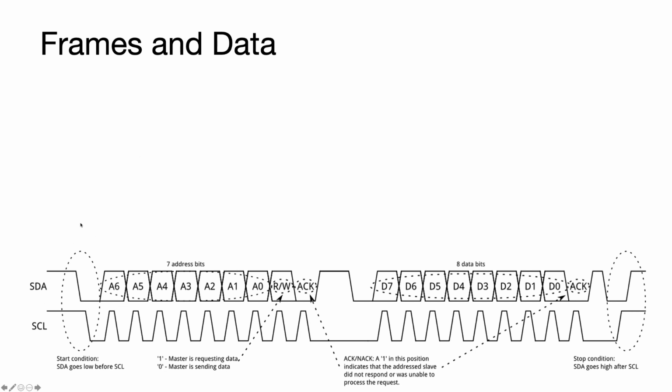So here's the start bit. We see data being clocked out, and this is what we call the command. The first part of the packet is the address, or the control block. Here's the address, in this case a 7-bit address. Then the controller is saying whether this is a read or a write. It should be R/W bar, meaning that a write is low while a read is high.